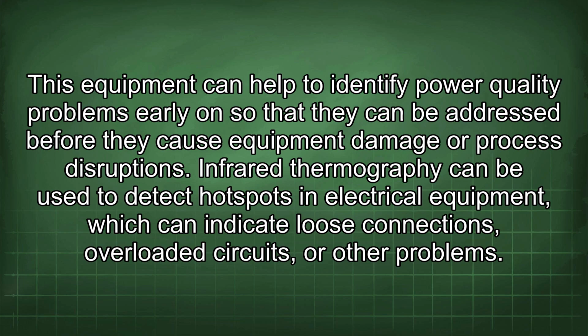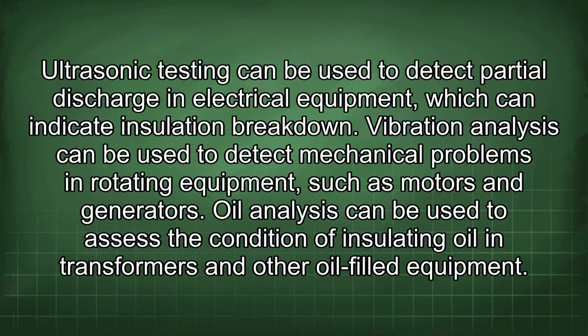Infrared thermography can be used to detect hotspots in electrical equipment, which can indicate loose connections, overloaded circuits, or other problems. Ultrasonic testing can be used to detect partial discharge in electrical equipment, which can indicate insulation breakdown.